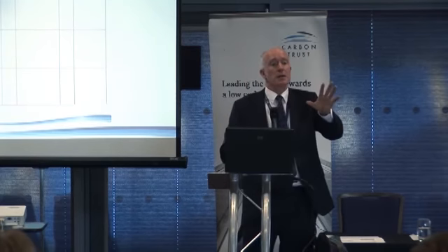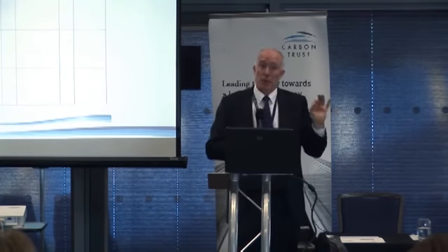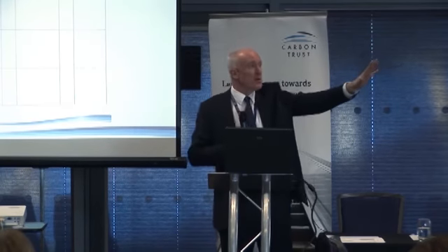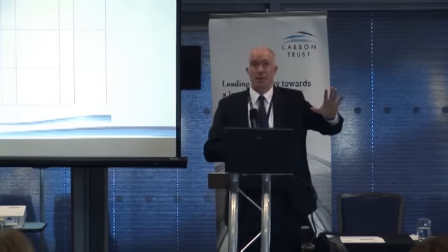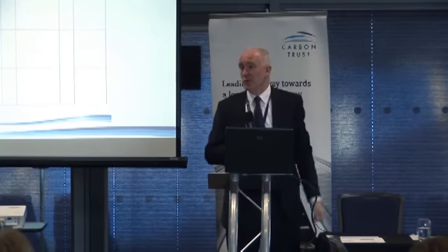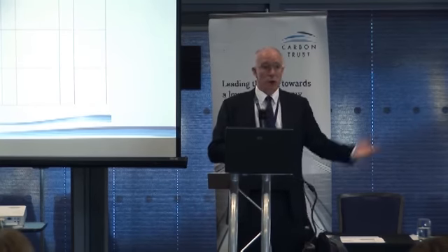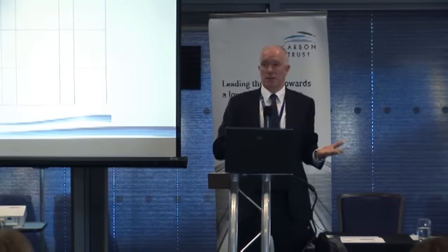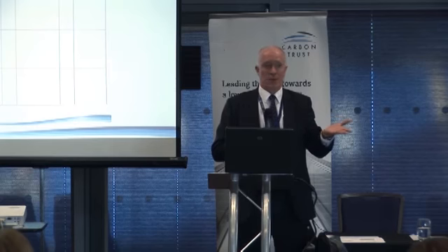More importantly, if we've got warm air, could we push that in through the ceiling voids? Could we put a damper on it, a control system on it, and when we're heating up our building, or when we need heat in our building, could we push the warm air into the ceiling void at 30 degrees centigrade? If we could, we push it in and have it coming through. 30 degrees centigrade is the ideal temperature for heating our buildings. Can we do that? And that's what we'd be thinking about.